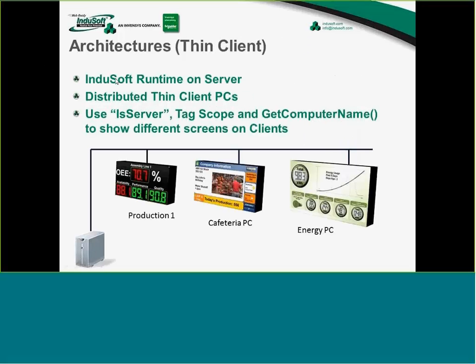PC. Now, taking this the next step is potentially having a thin client. And what I'm talking about here is really, at least the images I'm referencing, is the thin client that we call Secure Viewer. Now, Secure Viewer gives you the ability to remotely run your application. Essentially, all of the application is on a runtime PC server somewhere, and then the remote PCs, which would need to be less horsepower or maybe lower memory requirement PCs, would then get their information from that real runtime, and then as a thin client, display the screens and the data as necessary.